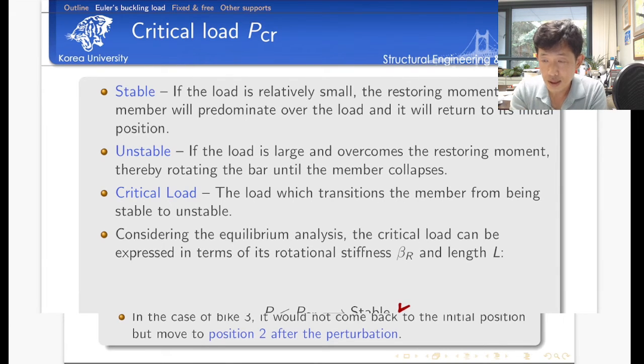It's like the issue regarding the shear center. Do you remember the reason that we discussed the shear center? Because we use the beam theory to investigate stress development in the beam. But if you apply load in an arbitrary direction, in the lateral direction, then it's going to produce torsional moment. Because we are using the beam theory, there is no way to handle this torsional moment, isn't it? That's why we need to find the right position to apply the load, not to cause any torsional moment. That's the issue regarding the determination of the shear center.